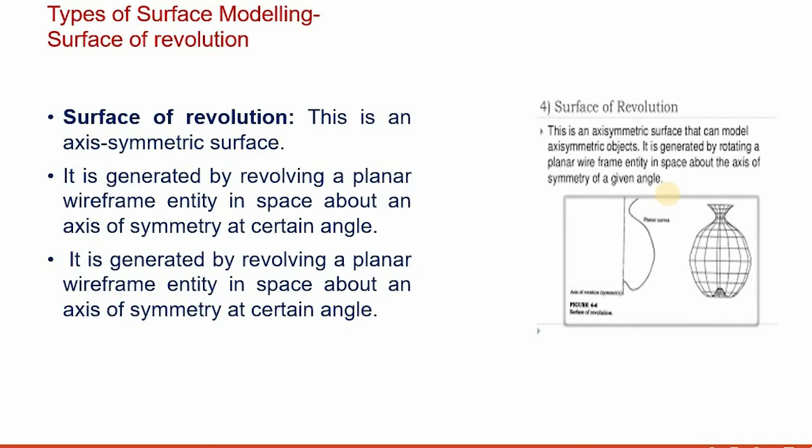Another type of surface modeling is the surface of revolution. The surface of revolution is an axis symmetric surface. It is generated by revolving a planar wireframe entity in space about the axis of symmetry at a certain angle.